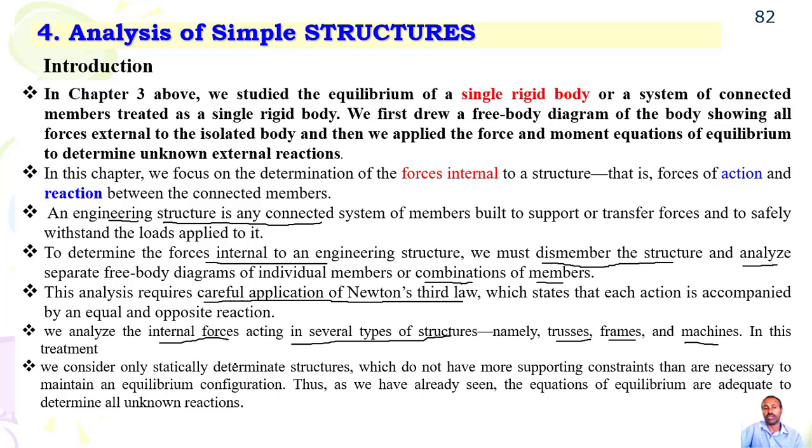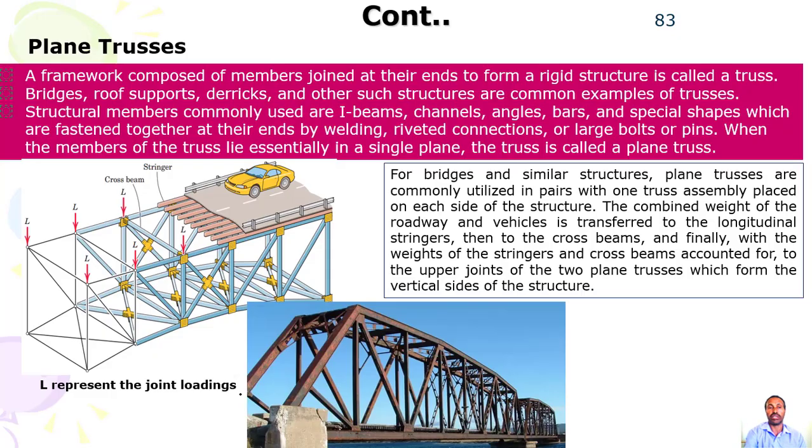In this treatment, we consider only statically determinate structures, which do not have more supporting constraints than are necessary to maintain an equilibrium configuration. Thus, as we have already seen, we will use the equations of equilibrium, which are adequate to determine all unknown reactions. Otherwise, we will need other techniques.